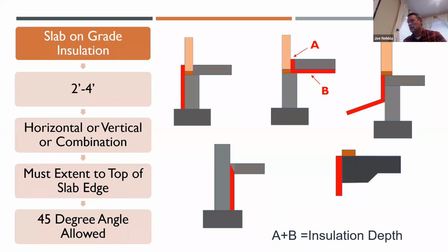And that table points to the basement, crawl space, and slab edge insulation sections as required. It's kind of how you get to this as a requirement. But that air sealing and insulation table in the current printing of 2021 accidentally references the crawl space section for the slab edge insulation. So it says slab edge insulation has to be installed per, and it points you to the crawl space section. Well, that's clearly an error. And in fact, it used to be the slab edge number and they just didn't move the number. That will be corrected, I'm assuming, in a future printing.